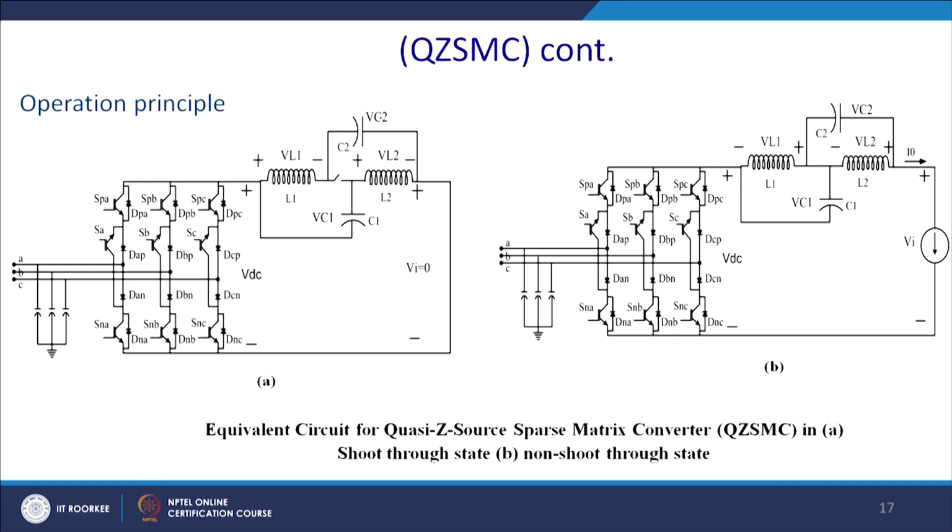So, you have an input stage working to generate the DC-link voltage, and you apply the shoot through into your inversion stage. Thus you will be boosting the voltages Vc1 and Vc2 above your VDC.